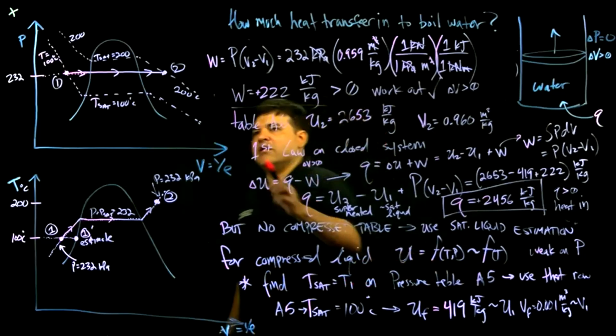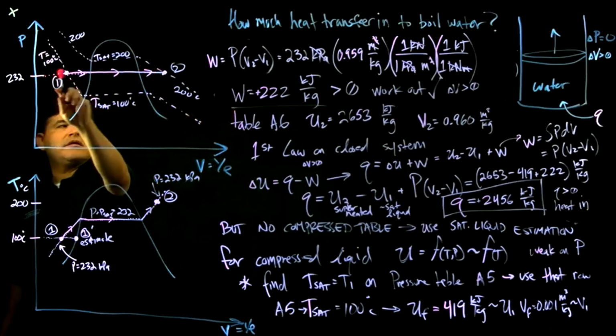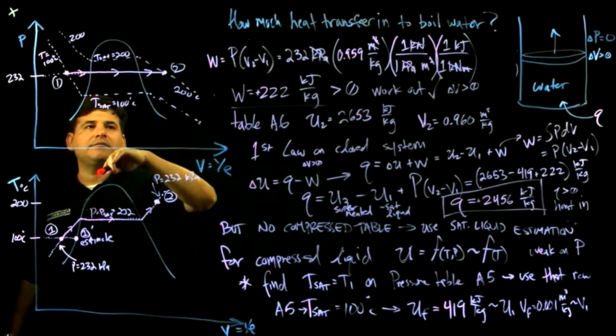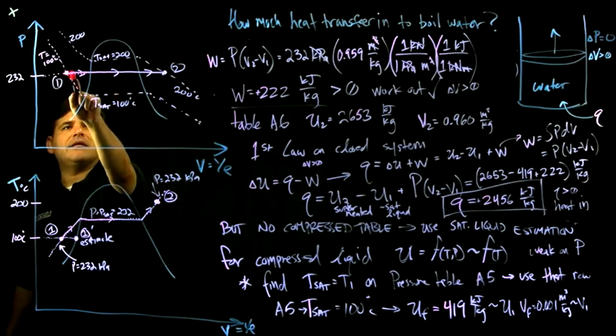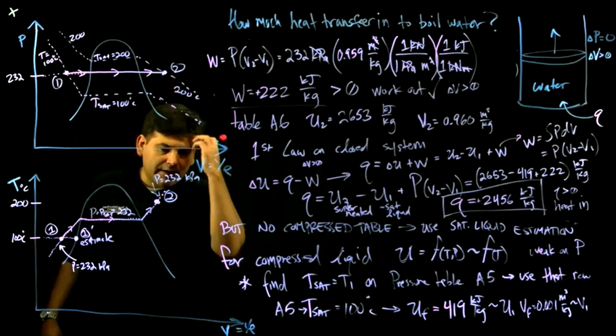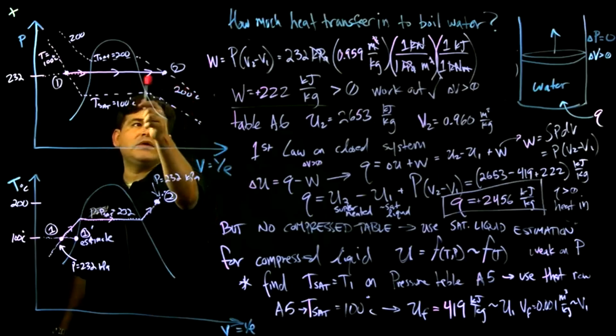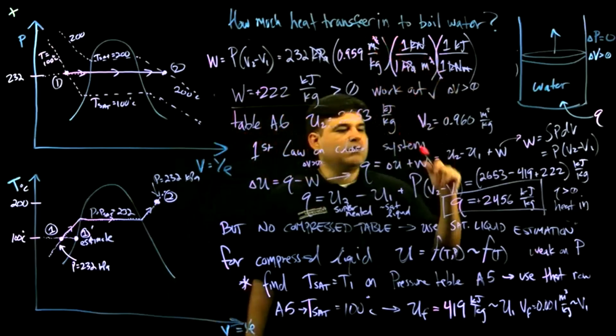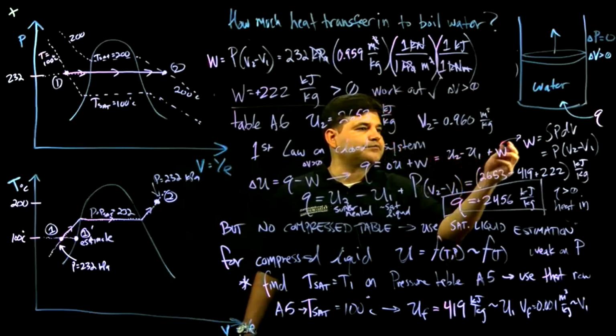This is how it looks on the pressure diagram. It's isobaric because the cylinder can move up and down, and that allowed us to follow this process on this PV diagram. Because the volume increased, in this case the piston moved, there's some work involved.